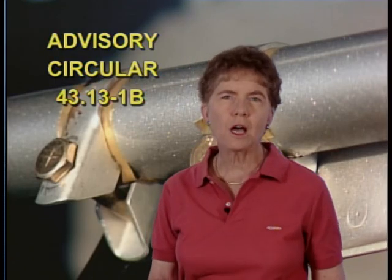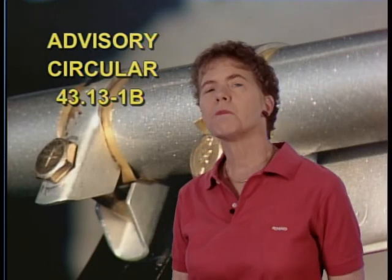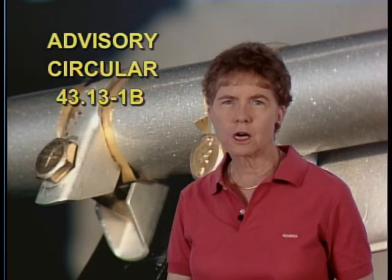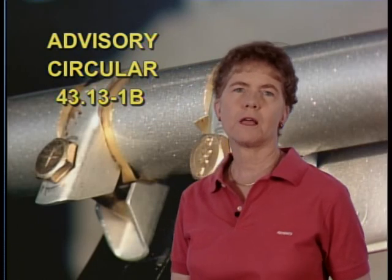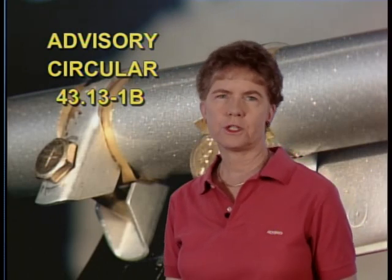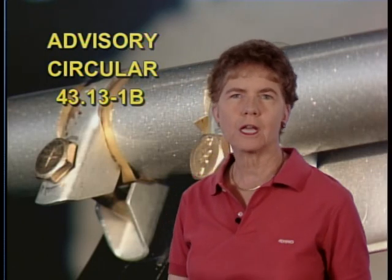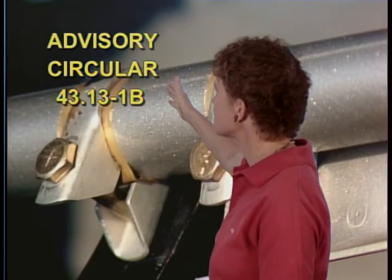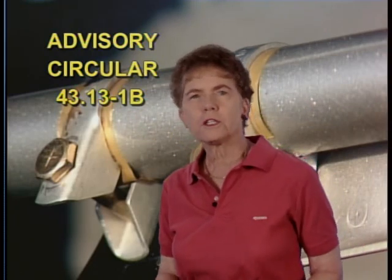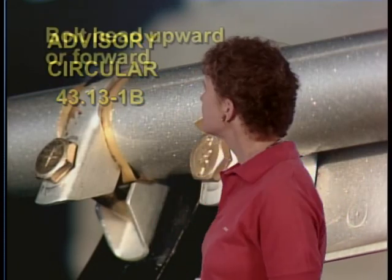You also will not find general standards, such as how far a bolt should protrude through a self-locking nut, in places like aircraft specifications or type certificate data sheets. Those documents are specific to an aircraft type and don't have that kind of detail. What's important here is where you find those standards for details such as the protrusions of bolts, studs, and screws through self-locking nuts, and you find them in this advisory circular, 43.13-1B.